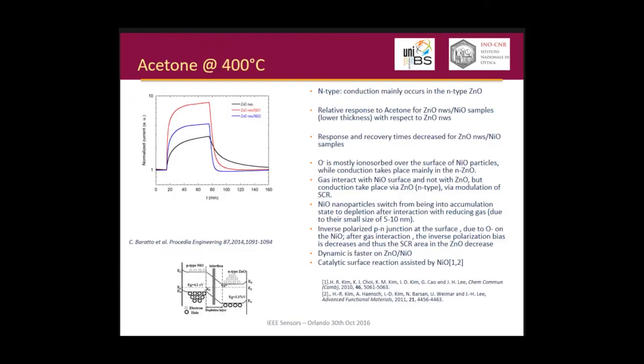And so what happens is that if you only consider zinc oxide, you have this type of response to acetone. If you consider zinc oxide plus nickel oxide polycrystalline nanowire, you will have an increase in the sensor response, this one, and a decrease in the response and recovery times, and the same for the other thickness.